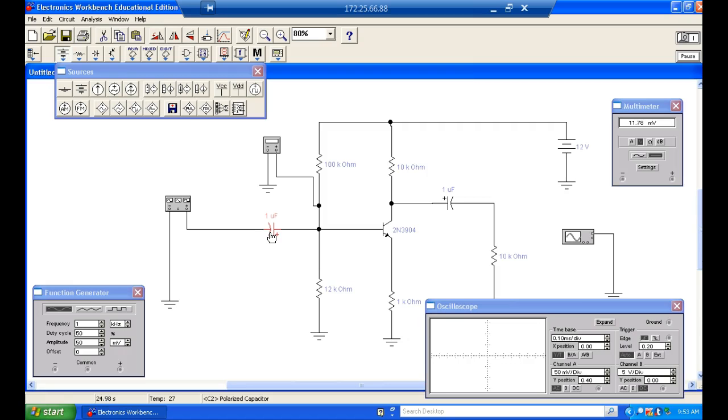So what two things cause this to happen? We've seen this before, a very low base voltage. Not the 12K. The 12K caused the base voltage to go up, right, and move towards saturation, right? This guy moved toward cutoff, but this right here went to basically 0 volts, right?